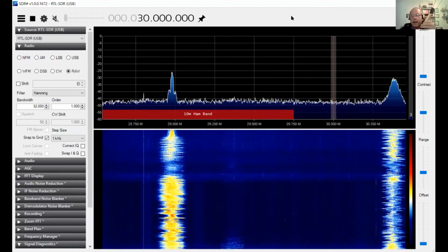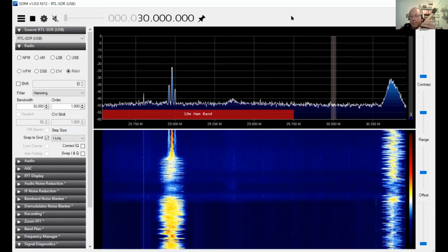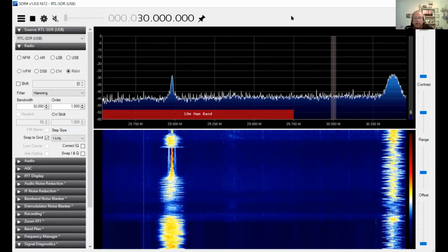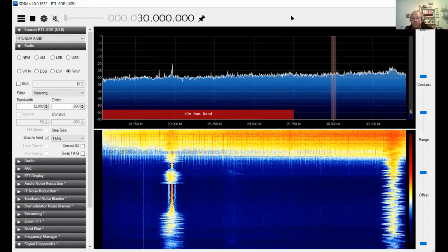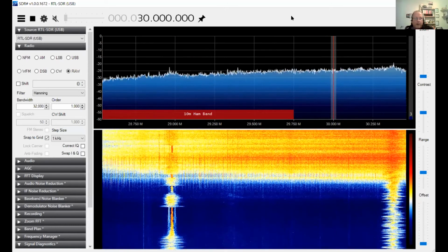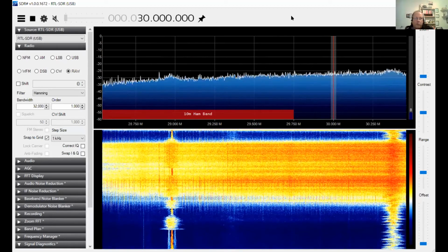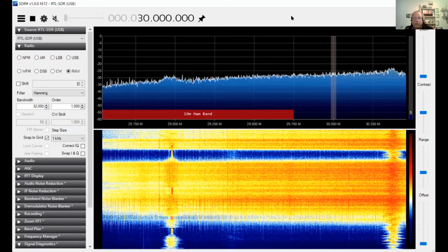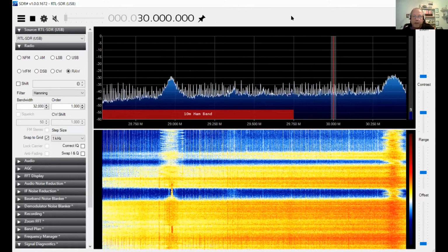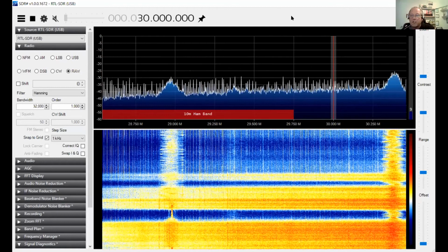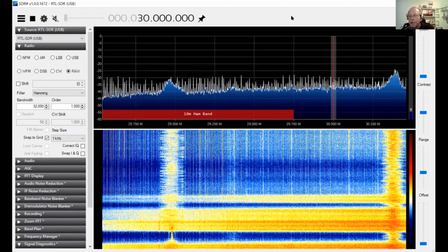However, I talked about computers, laptops can put out noise. I'm going to point this thing down on my laptop, and this is the keyboard of my laptop. Sure enough, it raises the noise floor almost 20 dB. And if I go up onto the screen, look at all the spikes of noise coming from the screen of the laptop, right?